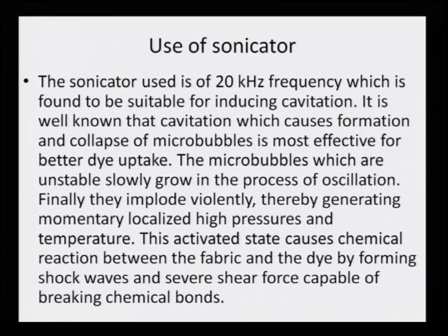The microbubbles, which are unstable, slowly grow in the process of oscillation. Finally, they implode violently, thereby generating momentary localized high pressures and temperature. This activated state causes chemical reaction between the fabric and the dye by forming shock waves and severe shear force capable of breaking chemical bonds. So, you see that at that kind of agitation, what happens to the chemistry of the dye and the fiber?